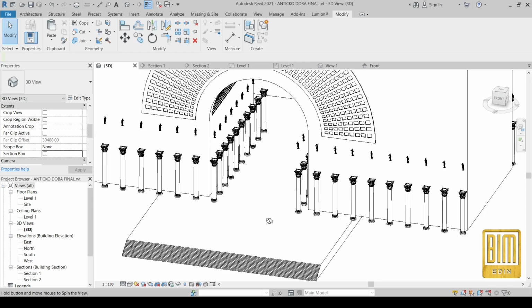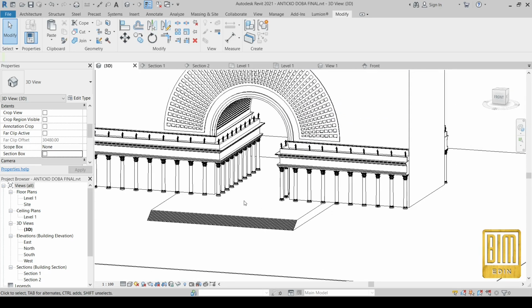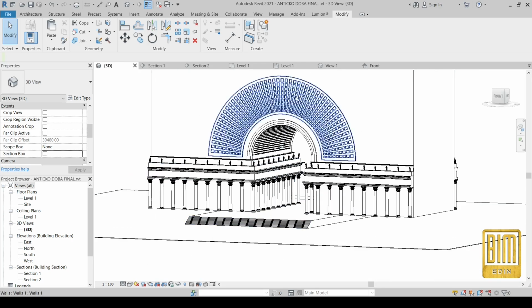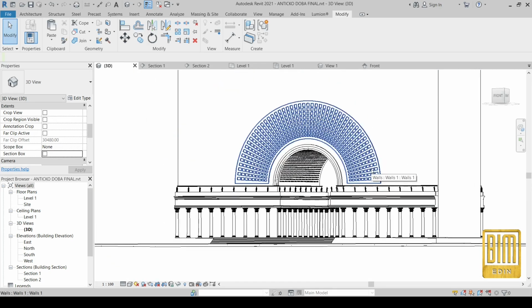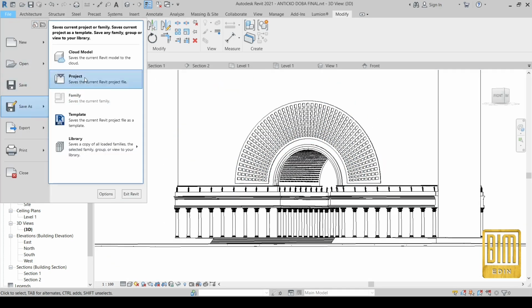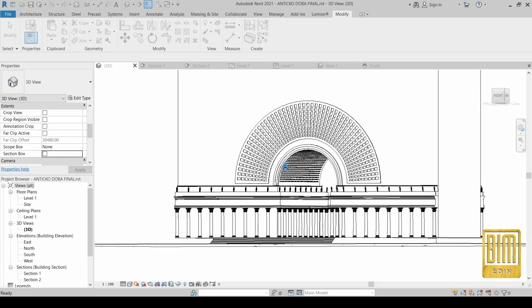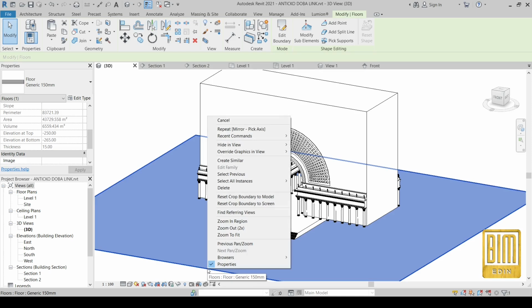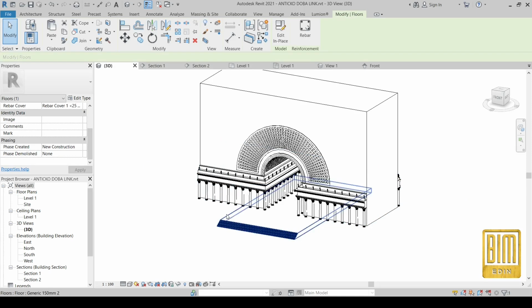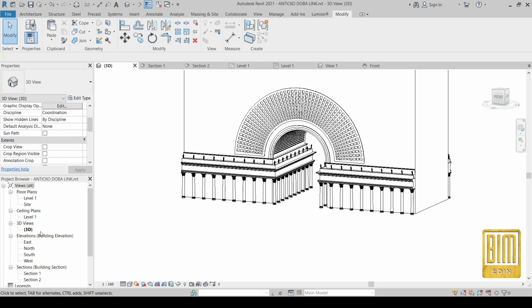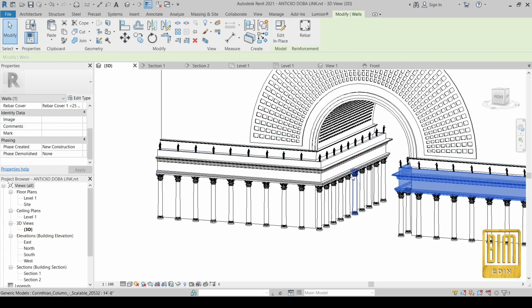As you can see, when we have this geometry created, it is very easy. You just need to position the middle of the model, and using the mirror tool you can duplicate this element, and in a very easy way you can create this kind of models in Revit.